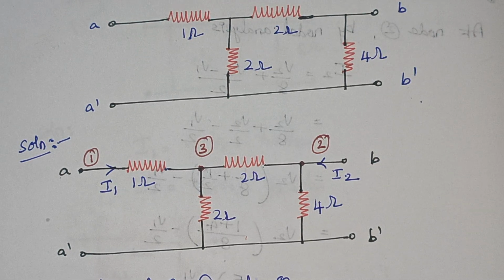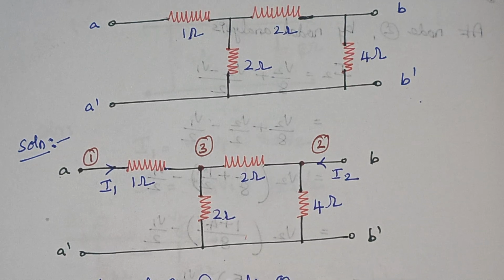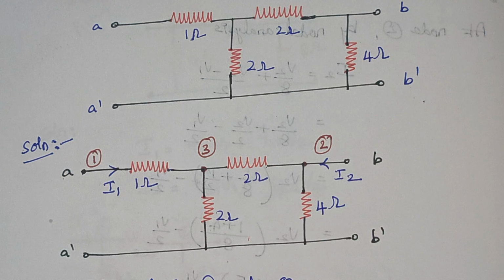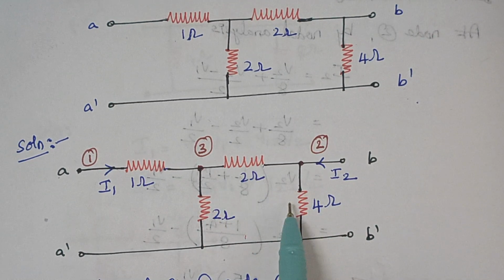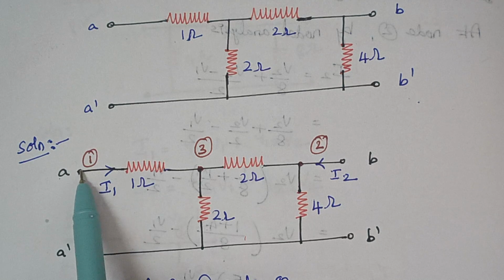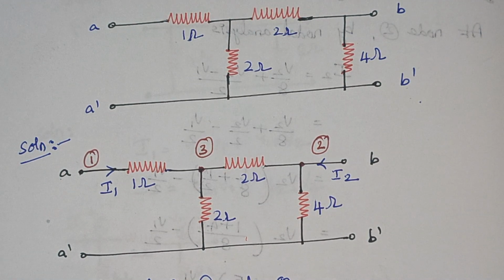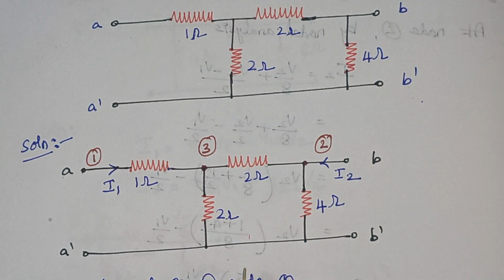the same circuit diagram, because it comprises only resistors. Now we are fixing the nodes. Generally a node is nothing but an interconnection of two or more elements. But here in this case, you see this is one node and this is one node, because two elements get connected. But here we are assuming this as another node to make our calculation easier and simpler. With two nodes we are unable to solve.